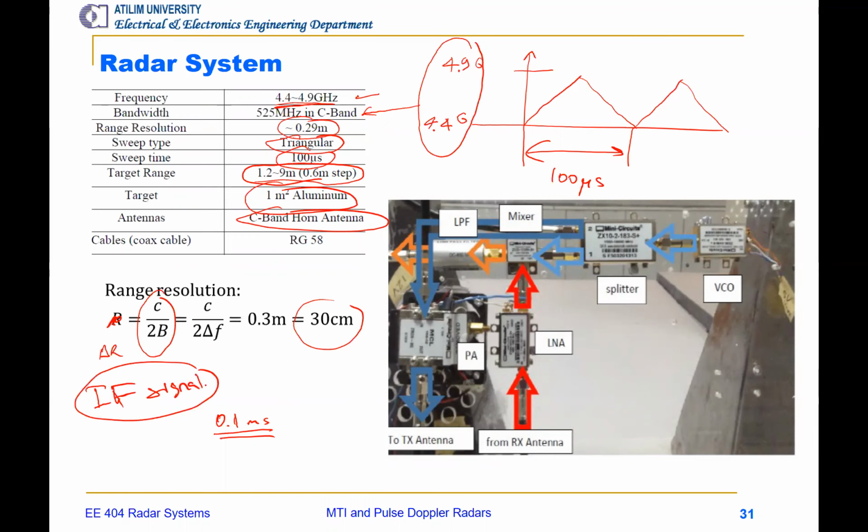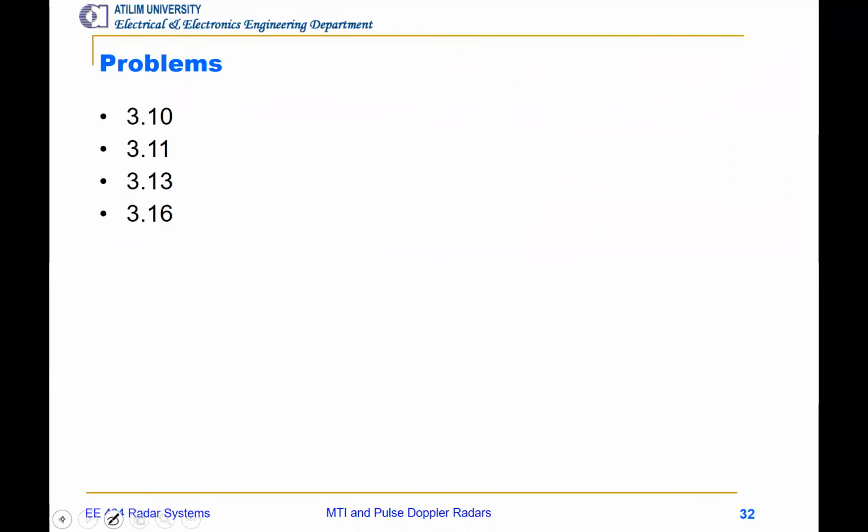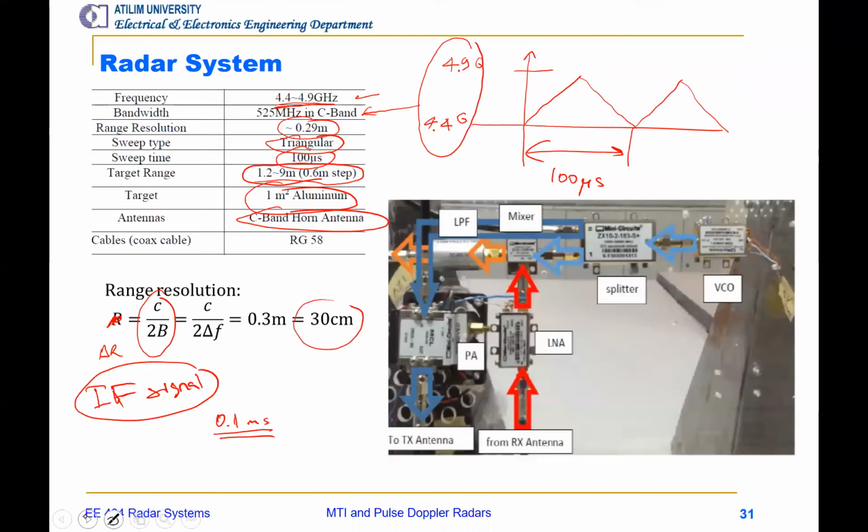We provide the IF signal and then show the bit frequency on the spectrum, or we use a digitizer to convert it and then show the bit frequency in the spectral domain. We can easily implement a peak search and then determine the bit frequency and determine the range and speed appropriately, okay? So here is the system that you'll be building in the next 2 or 3 weeks.